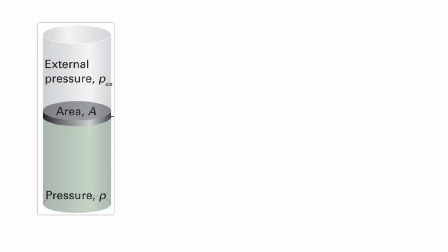We've called that irreversible work, mostly to recognize that it's only going to happen one way and does not spontaneously reverse its direction. So what if we take that to the limiting case? If we could make the change in volume so small that the pressures are never actually different, we could see the piston reverse course spontaneously.